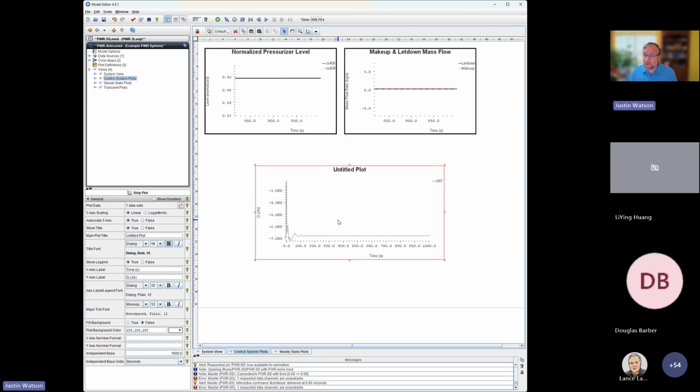When you add them together, they should match the total energy into the system. If they don't, then you may have to figure out why. And I'll give you a little hint, they won't exactly match, and it's because we didn't model all of the heat transfer in those steam generators. So think about adding or modifying the control procedures to include maybe some additional cells to make that calculation more accurate.